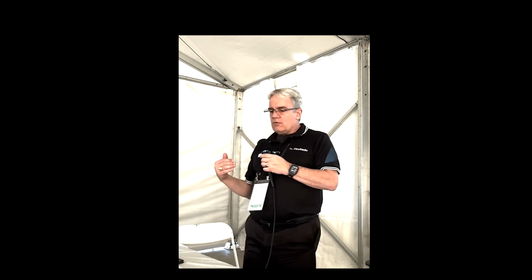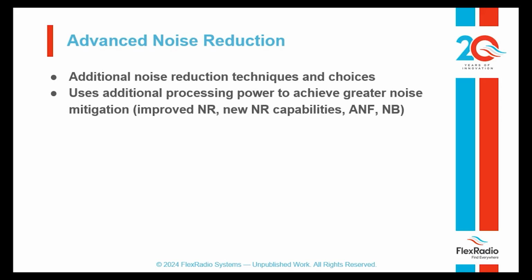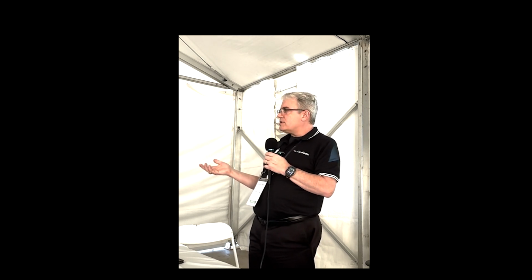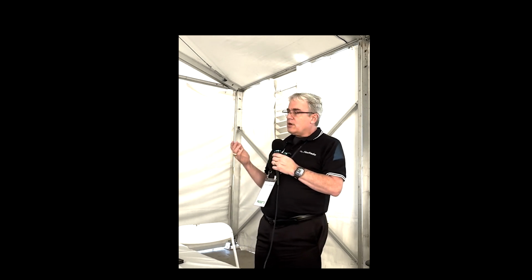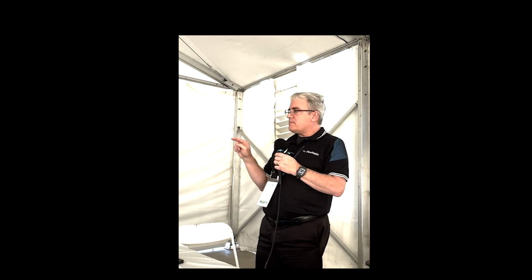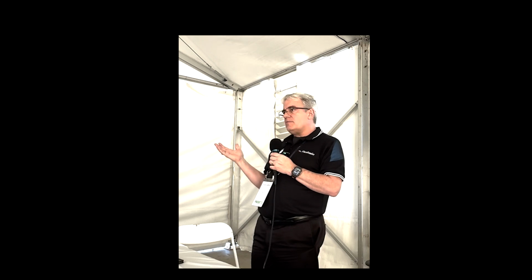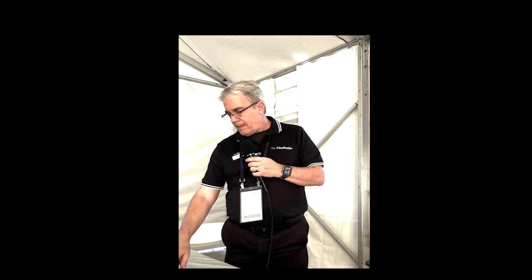We have some advanced noise reduction capabilities we're going to put in the radio that need more CPU power. We've already added an integrated NTP server. Because we have the GNSS receiver in there, it has an NTP server. This means you could go into the field and run WSJT, which is a time-sensitive application. You can point your computer at the radio and say, that's my time server, and it will serve time over NTP for you. So you don't have to have some other kind of time source.